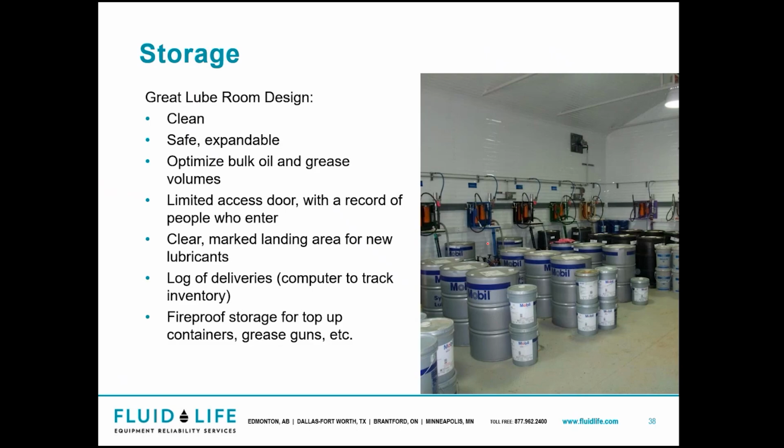Now, I talked about having your barrels stored on their side. I can't really complain about the picture of this lubricant storage. Everything is pretty good. The only thing I could criticize is you can see how everything is marked on the walls here. The labels could be bigger, and they could be color matching. And the other thing is you could paint the floor for your landings to match each of the colors. Having different colors and color coding for lubricants is just that one extra step. So you say blue, okay, I know blue is my Hydro 46 oil, and then you can just look for anything that's blue and know that's how it's associated.